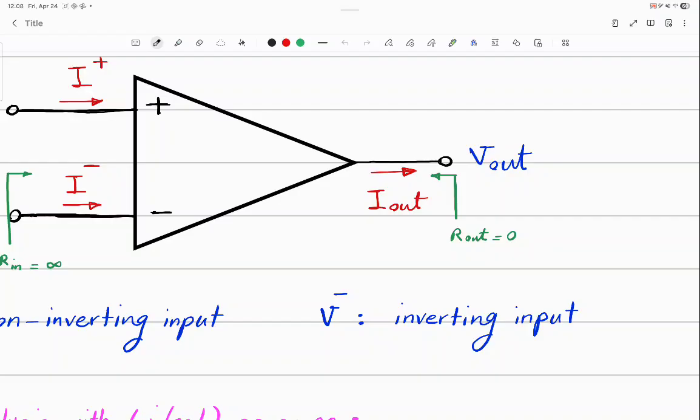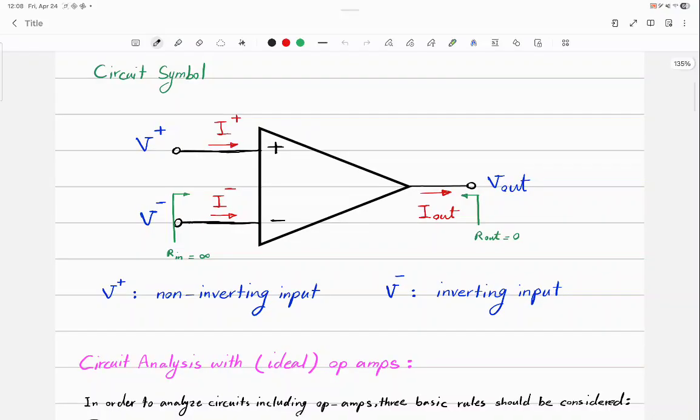So the other terminal is ground, okay? So when I'm saying V out is the voltage at that point, it's measured with respect to ground, okay? So R out is equal to 0, actually, based on the internal circuitry of the op-amp, okay? These are all points that could be a question from the conceptual part of your third exam.